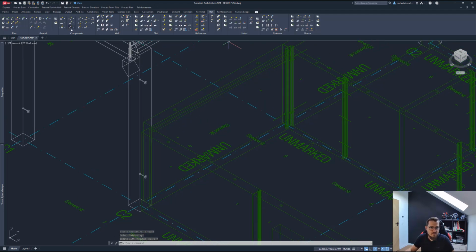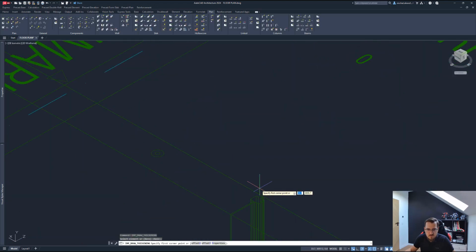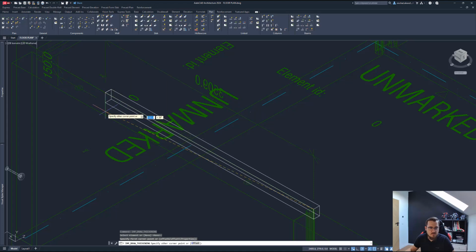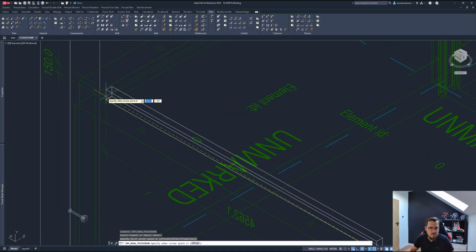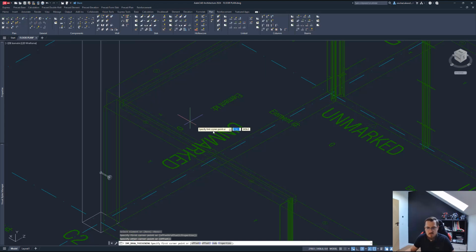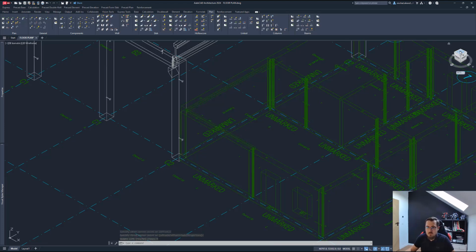Let's maybe add panel thickening as well for this wall, just so we're consistent, right? And it's going to be the same thing. And let's accept that. Okay, and let's do that from this point. Right, and you can see the preview. Maybe working in 3D is slightly better for this. All right, let's snap that to the bottom, and like that. Like that, we have a panel thickening. Let's accept that, update lifts, and now we have panel thickenings, which is perfect.